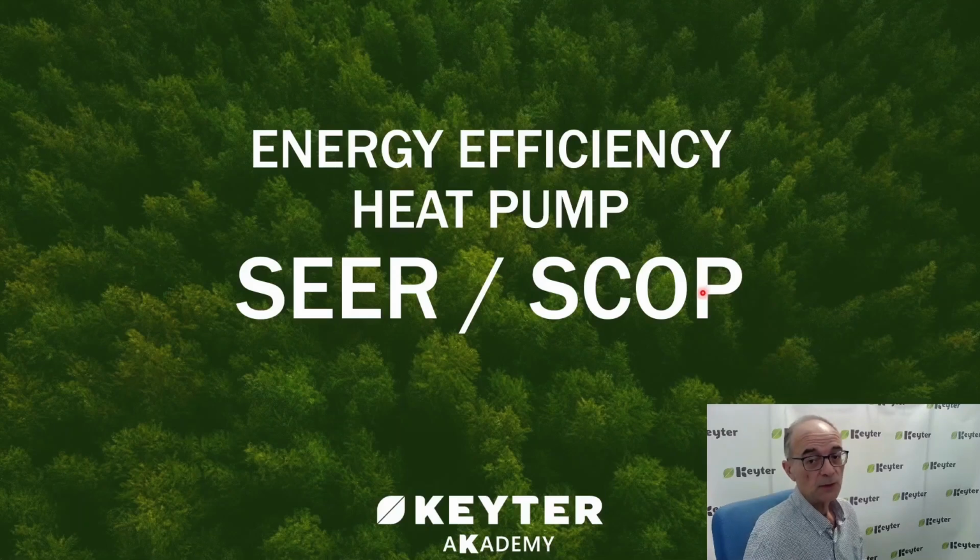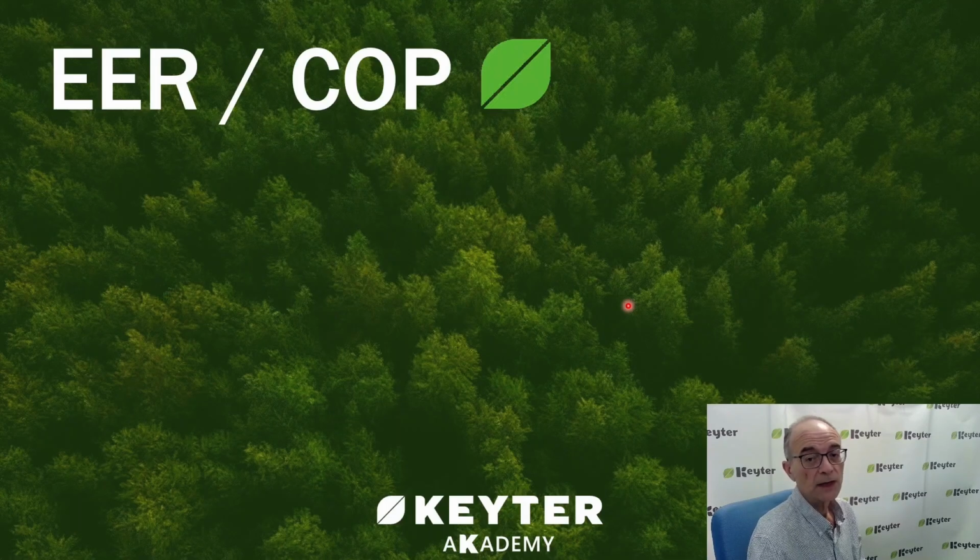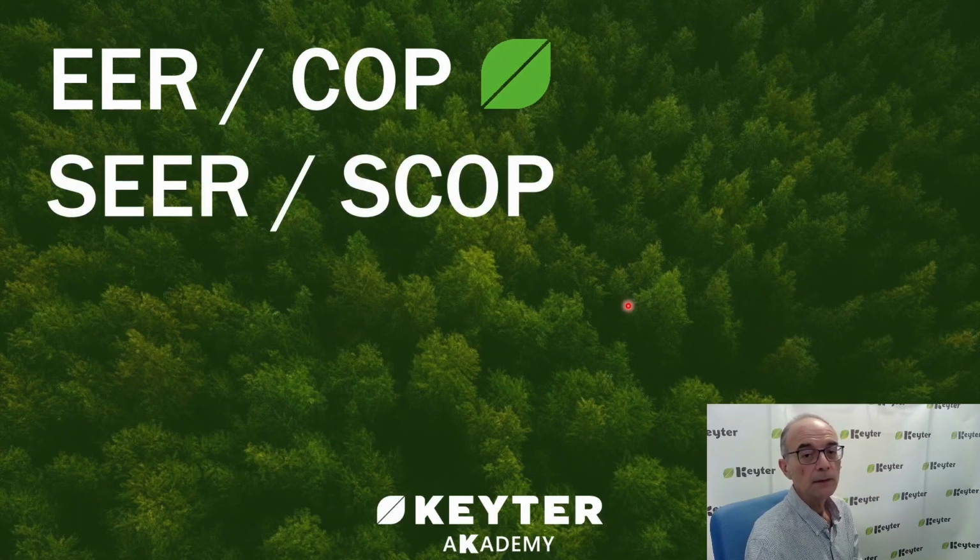In this video series about the energy efficiency of heat pumps, today we're going to talk about the seasonal SEER and SCOP, SEER for cooling mode and SCOP for heating mode. In previous videos, we had already defined what the EER and COP were, which were instantaneous values, meaning at a specific moment, a snapshot of the machine operating under Eurovent conditions that were defined for the unit at full load. Today we're going to look at those seasonal values.